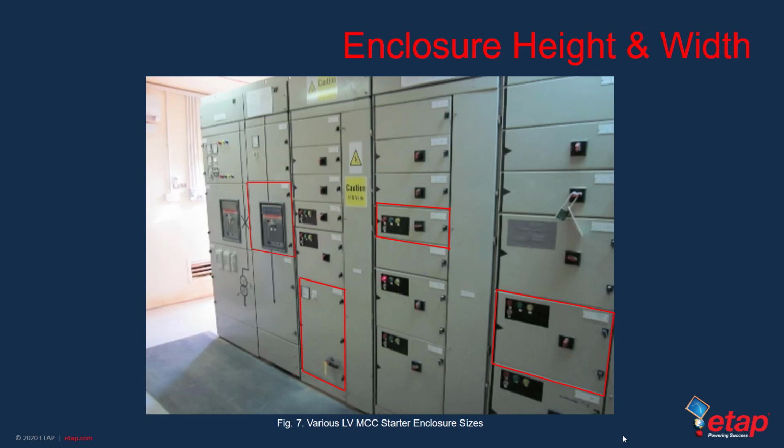One very popular source of concern as well, when applying the new IEEE 1584-2018 model, is the determination of the proper dimensions for each location. This new standard has introduced the dimensions as an input and as a direct parameter in the calculation of the incident energy in the equipment. However, it is very unlikely that we're going to measure and capture the width, height, and even depth of each particular enclosure and represent the equipment one enclosure at a time.